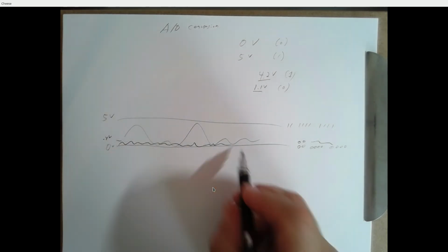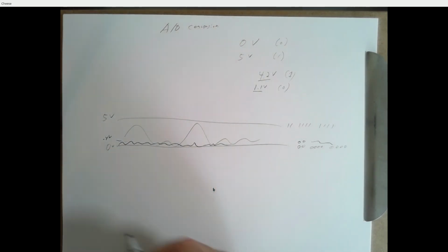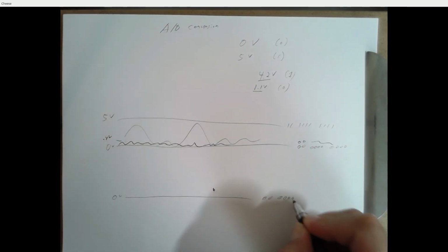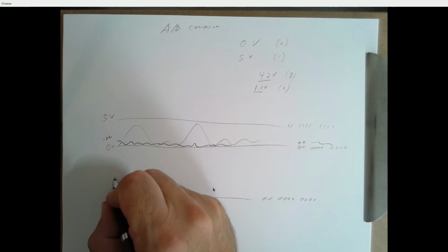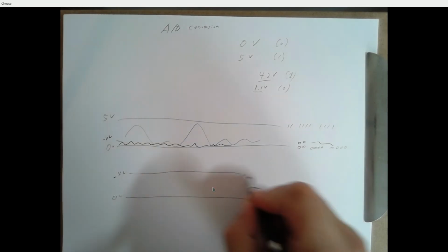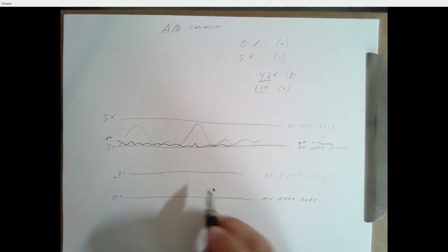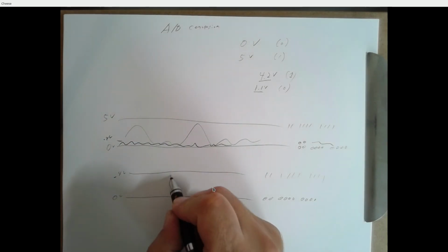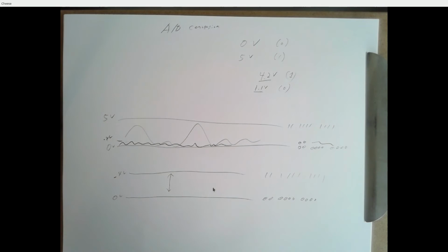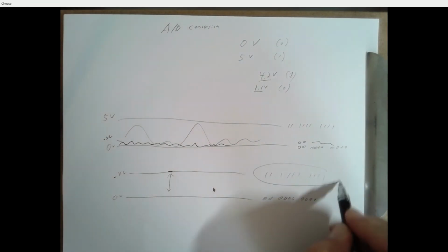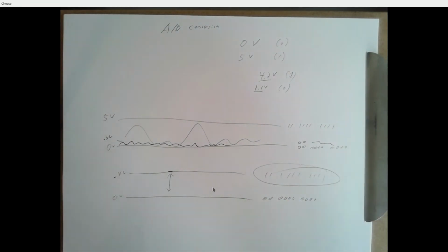we expect to see. So we would like to calibrate the system and say, okay, 0 volts is going to be all zeros, and maybe 0.4 volts is going to be all ones. So now we've got a full 10 bits to represent every voltage level between 0 volts and 0.4 volts. And the understanding is we're not going to put in anything bigger than this, because if we did, we'd need to convert it to a number bigger than all ones, and we can't do that with just a 10-bit number.